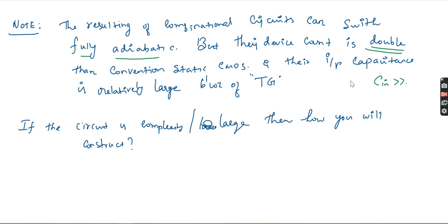When you think about power dissipation, if the input capacitance increases, the power dissipation will also increase, even though the circuit is fully adiabatic.